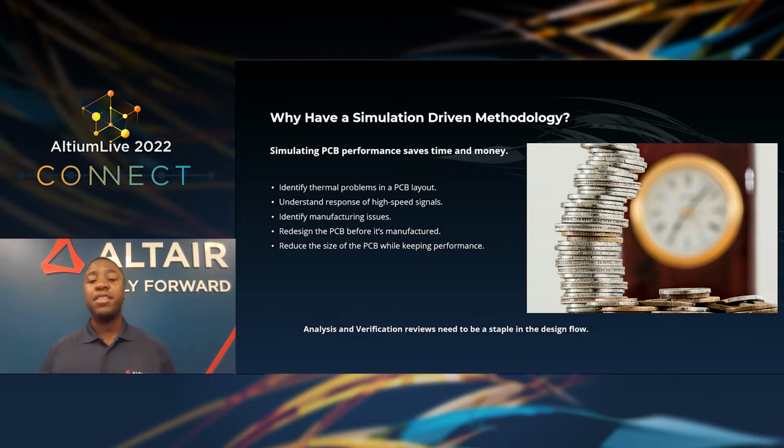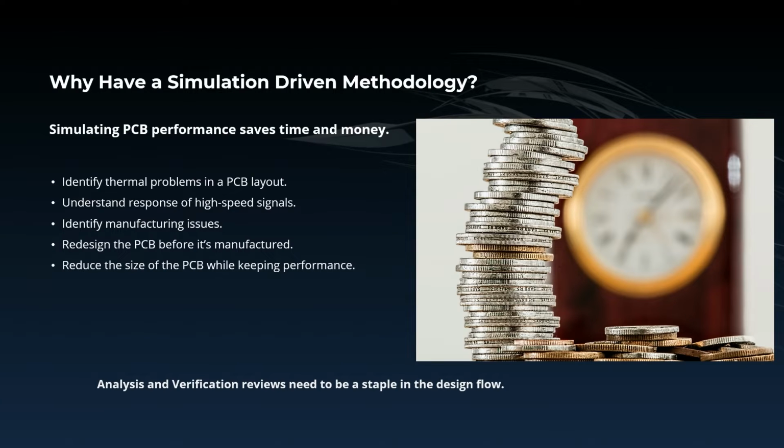So let's first understand the why. Why have a simulation-driven methodology? It comes down to saving time and saving money. This is done not only through problem solving, but also through optimization. Simulations allow you to problem solve by identifying concerns and challenges before the board is released. Simulation also allows you to understand the manufacturability of your board. This includes design for electrical and design for manufacturing checks.